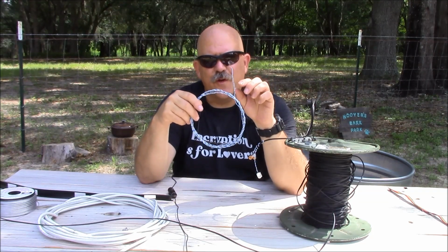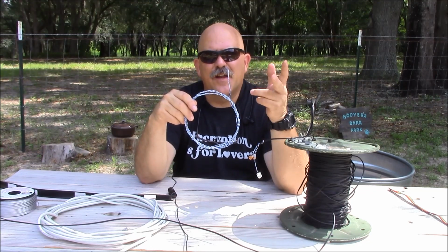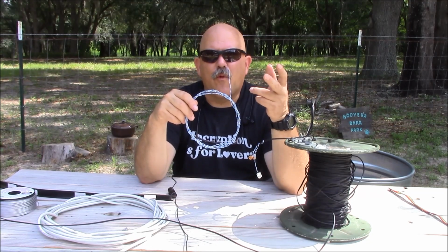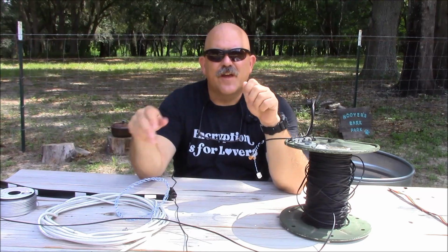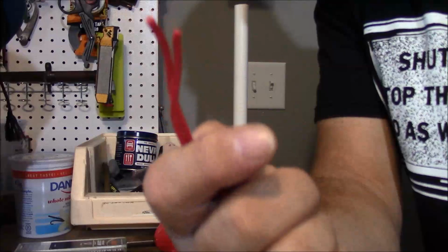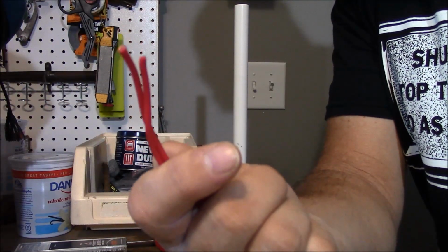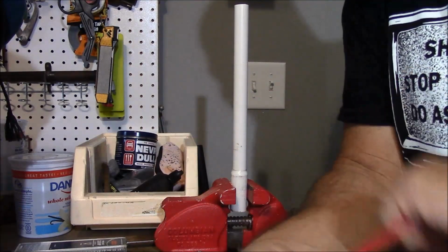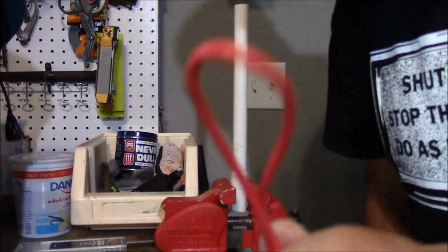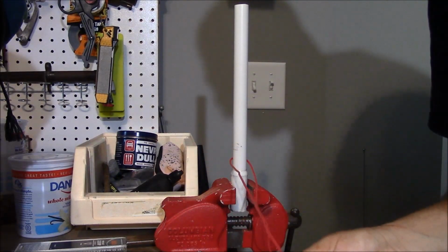And also, twisted pair is the easiest way for you to fabricate a feed line out of, say, some hookup wire, for example, by just having uniform twists. To make your own twisted pair out of standard hookup wire is pretty doggone simple. Just take the desired length of it, whatever you have, and just fold it evenly on itself, and then place it around an object, such as this pipe.